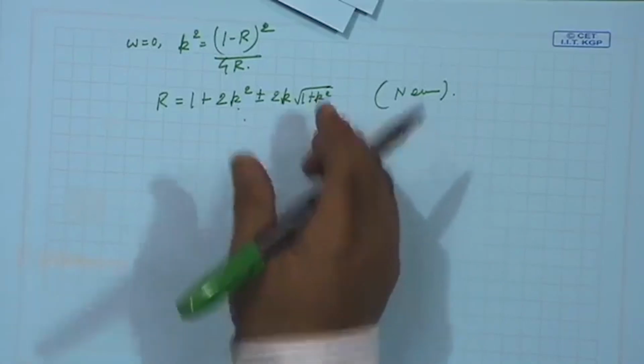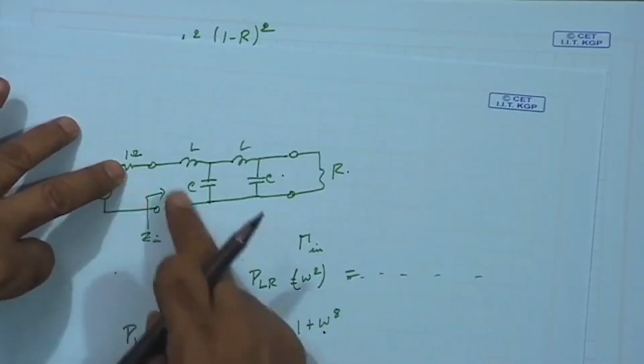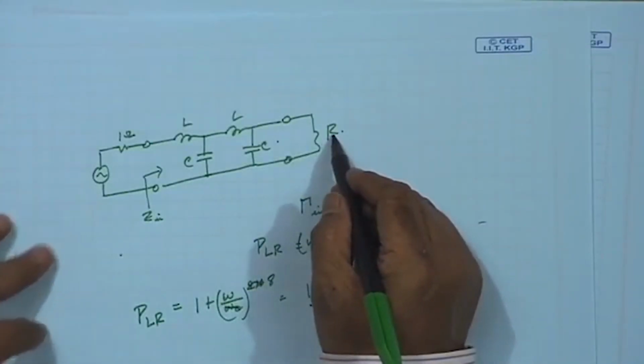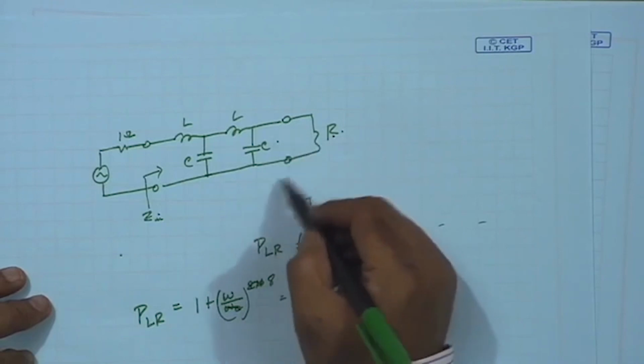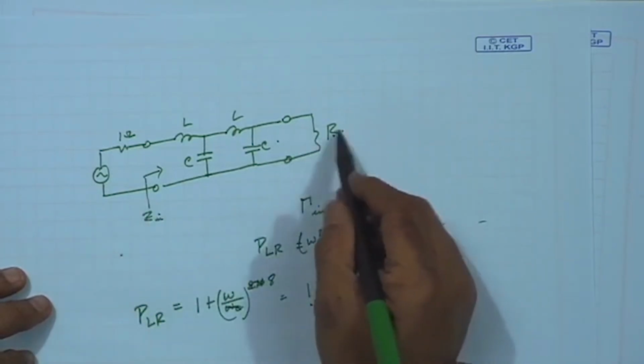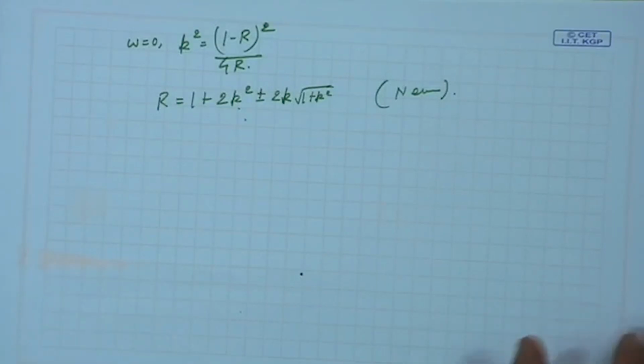That means, you see from the basic design there is a problem that where is that? Yes. So, I have taken this as 1 ohm, source impedance is 1 ohm, but your this r is not coming as 1 ohm, it has some value. So, there will be some reflections here. Also, depending on that r value, Z in may not be 1. So, there may be reflections here. So, filters generally are not matched.